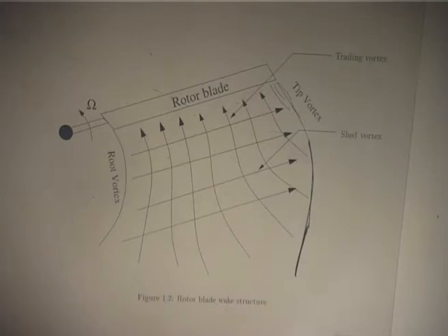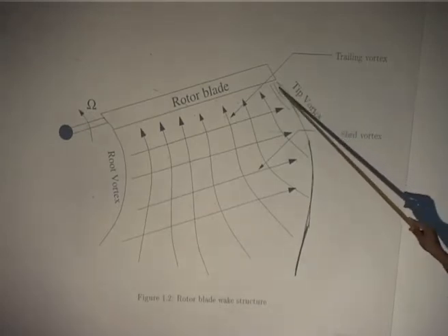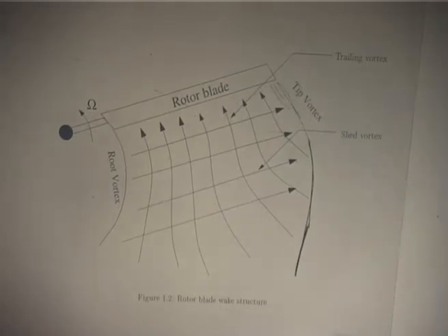That is your lifting line theory. It says that my circulation is constant, it comes out. That is called the trailing, because it trails, and that vortex will be like this. In the sense, usually I will draw from the point of view of clarity. Suppose you take a simple wing, just a wing.